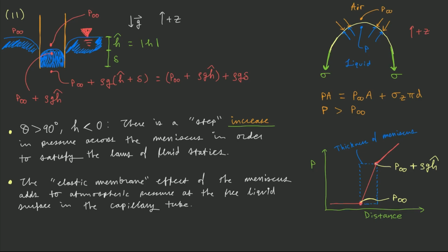So for example, if you're designing a manometer and you're trying to track the free liquid surface within some reservoir such that you can correlate the elevation of that free liquid surface with some pressure in your system, and you're using a photoelectric sensor or something of that kind to track that free liquid surface, you may want to subtract the effects of surface tension to more accurately predict what your pressure is. Now, in that case, Jurin's law will probably give you a pretty good estimate.